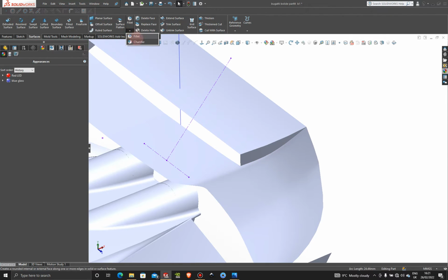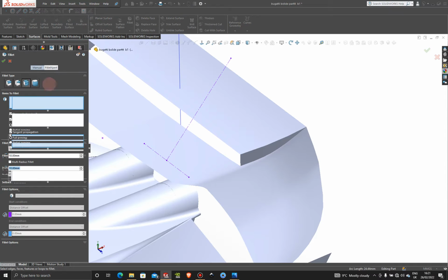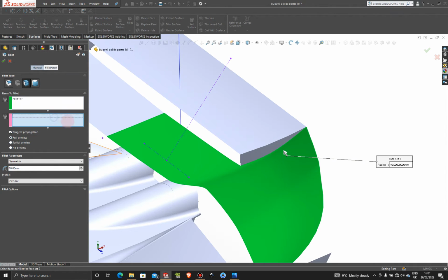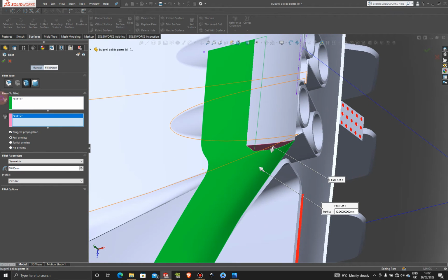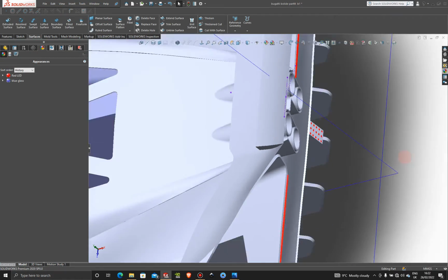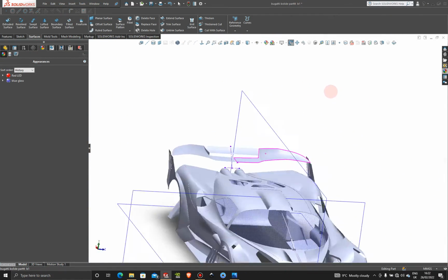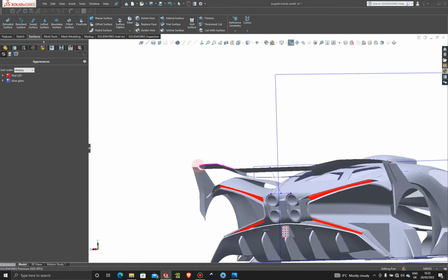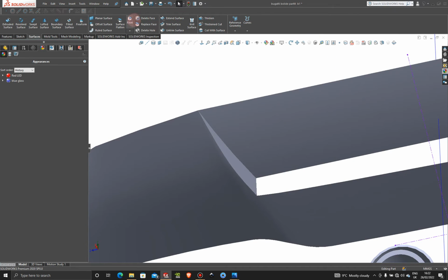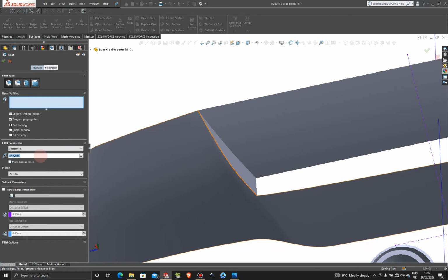Let's try a face fillet between this face and this face, and let's flip these. At first, let's just put here one, see if that will let us do that one, and then let's try and flip these points. No. Okay, so we're gonna leave it as is, and then that actually looks pretty good. And see if we can add a small fillet on these edges here.